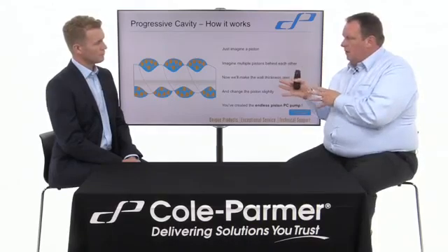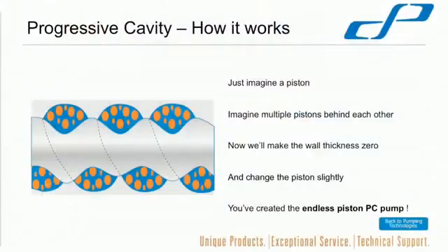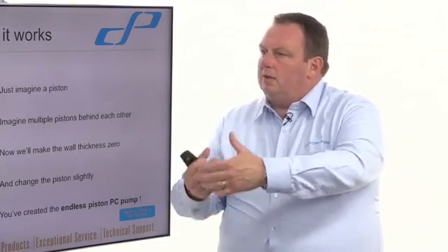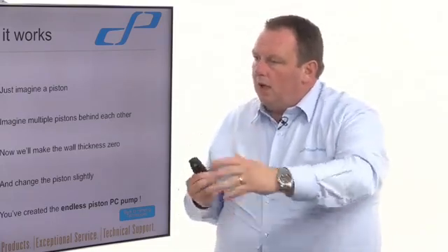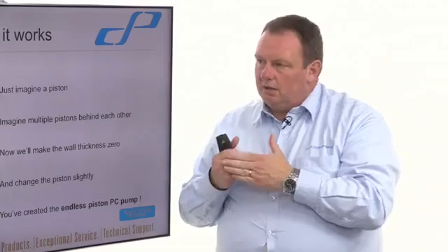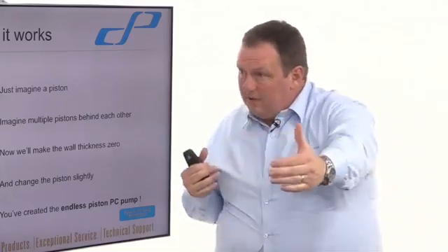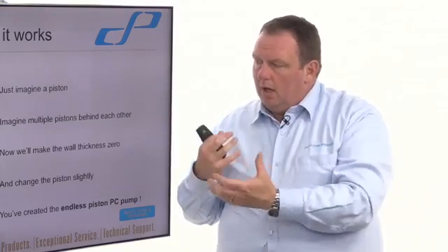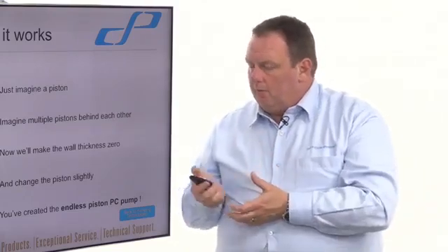So as I said, there is potentially another option of what can pump these things, but it can't achieve the same pressures. These can go to greater pressures, and you're talking in excess of 10, 20 bar in certain instances. It's down to your sealing arrangement, the motor driving it, and the length of the rotor and the stator. So if you wanted a greater pressure, you could have a longer rotor and stator. You have to go bigger on a very specific scale to get greater flow rates, but as I say, they're very good at what they do.